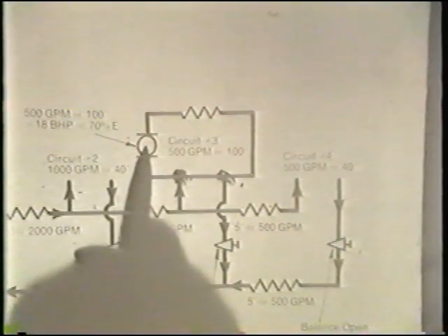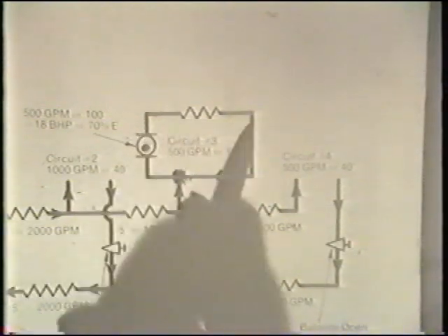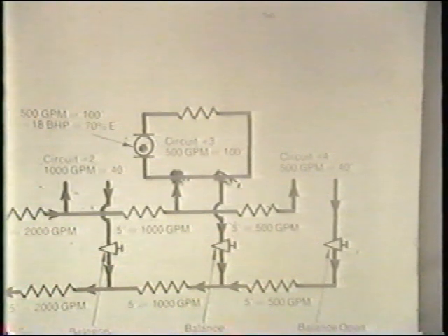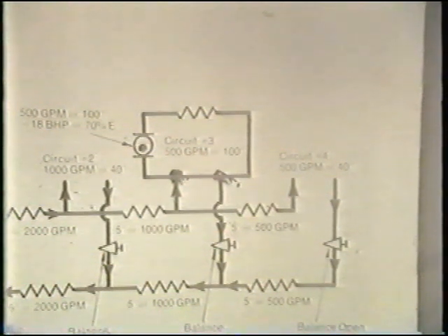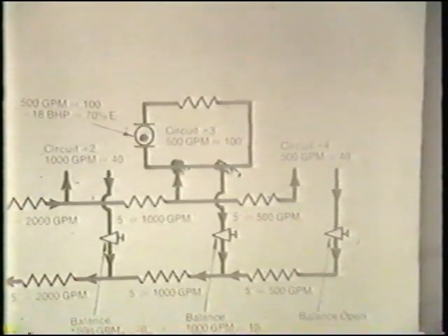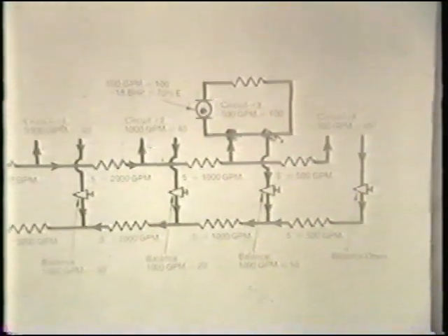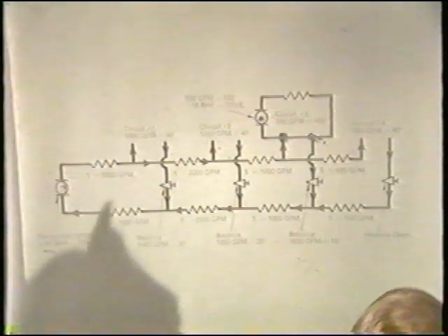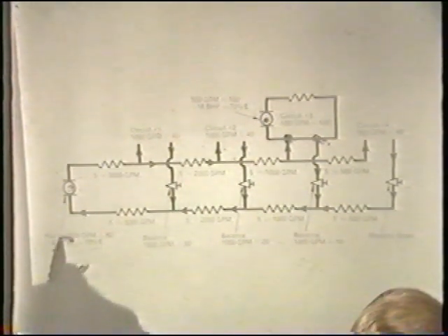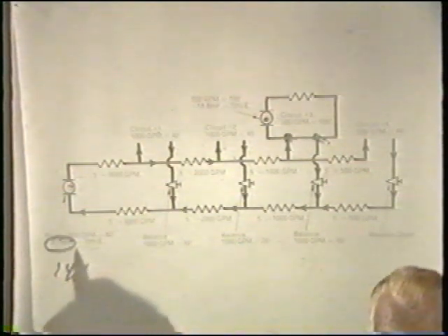We can then utilize a small pump to circulate the separate zone, utilize the major pump for circulating the other zones, but decrease our pumping power draw very considerably from 148 horsepower in this example down to 87 horsepower.